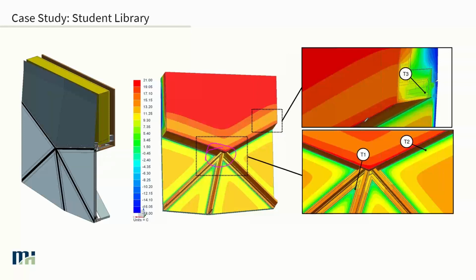And what does that do to the temperatures at that location? As we get farther out from that area, it should line up pretty well with our 2D analysis. You've got very consistent temperature gradients, so that should line up fairly well, but you're not able to capture that intersection of all these different components simply by doing it in 2D.